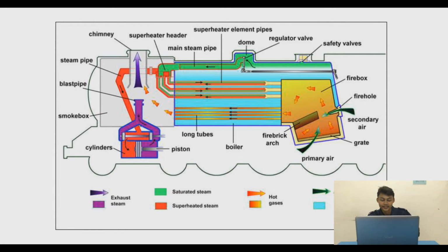There are two sets of piston cylinders, one set on each side of the train. Steam engines on steam locomotives are so-called reciprocating piston engines. Each set has one cylinder with a piston connected to the driving rod, which is then connected to the driving wheel. The other cylinder contains the slide valve, which allows steam to enter and exit the piston cylinder. This way, the piston is pushed once from both sides to complete one rotation, creating that reciprocating motion, which is then used to rotate the drive wheel.